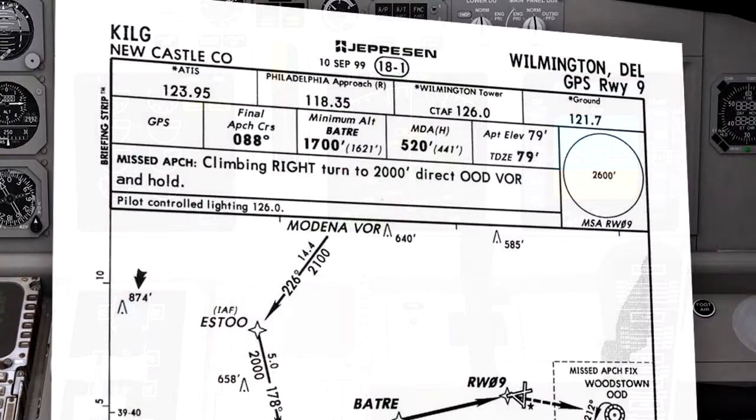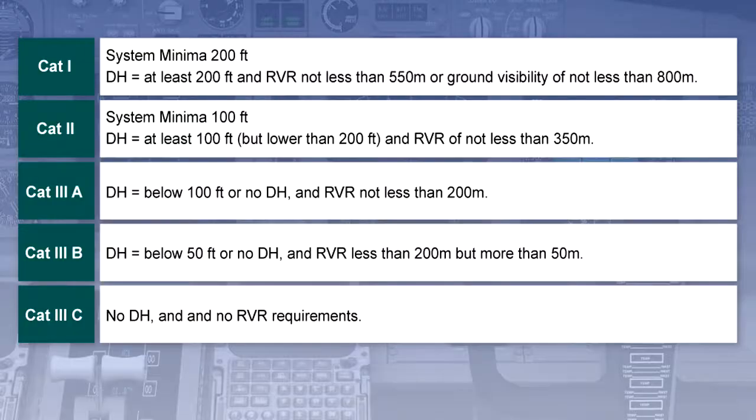The use of increasingly accurate technology, specifically ILS and FMS systems, has meant that this visual element to the precision approach is being reduced to its minimum. ILS systems are categorized by accuracy of operation, and this results in a specified decision height or altitude and minimum RVR requirements. Both ICAO and JAR have their own defined systems, but we will teach the universal ICAO requirements. You can see from the illustration the differing categories apply to decision heights.